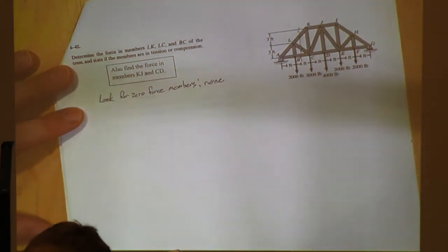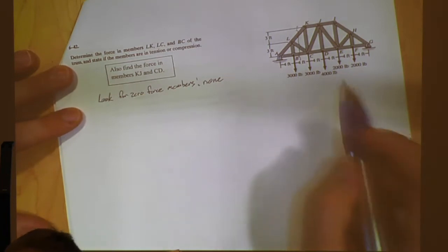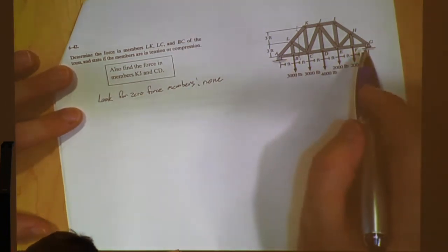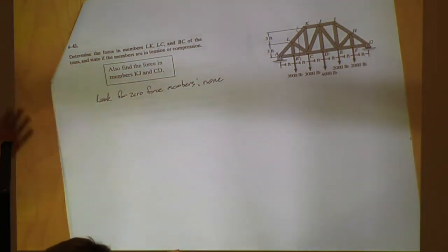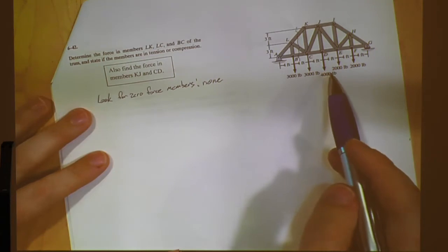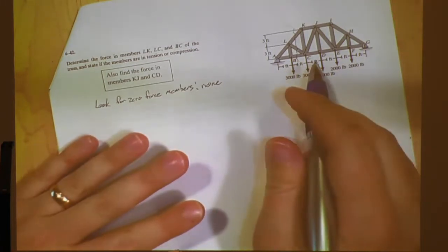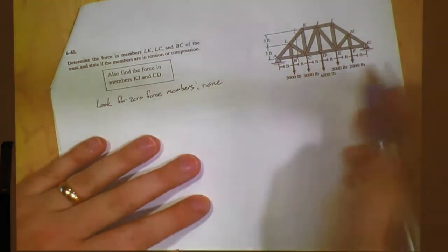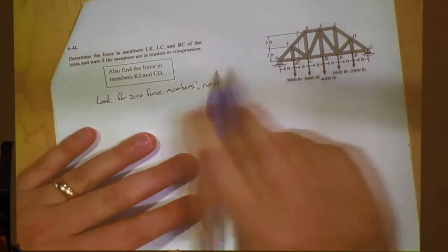If we had an actual horizontal force going there, then you would be right. It would reduce the force. However, there's not going to be any forces in the x direction for reactions because when we treat the truss as a rigid body, we're only going to have y reactions, right? Because right here, do you see any external forces in the x direction? No, so we're not going to have any reactions in the x. Will we have reactions in the x in the truss? Most likely. But we're not going to have the reactions have any x forces, right? So you can do it from either side for your section.